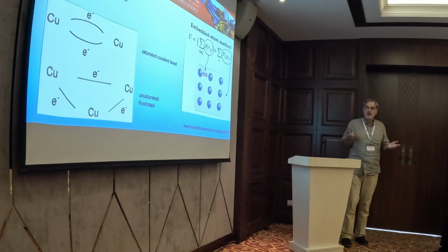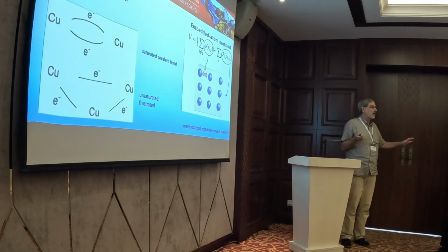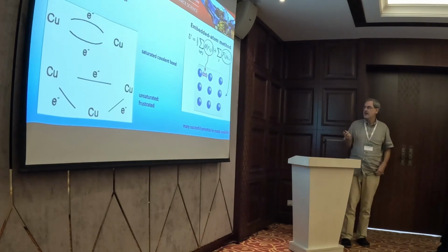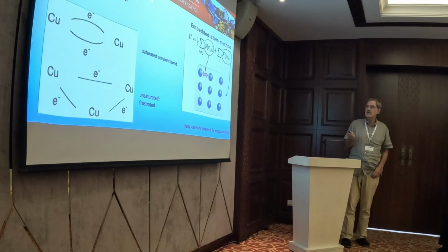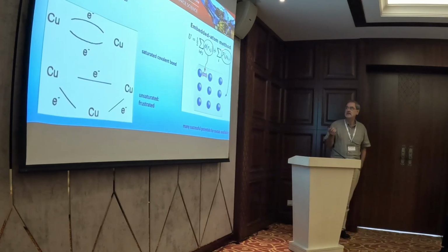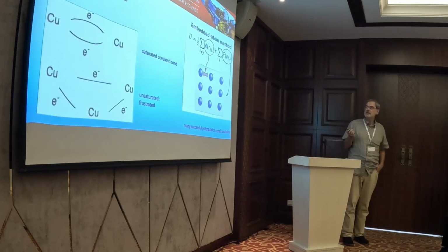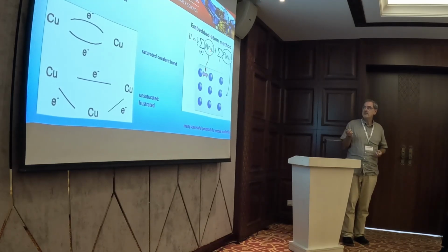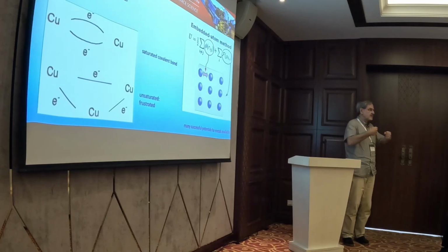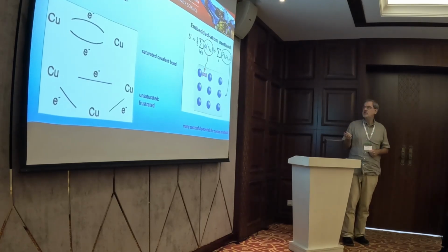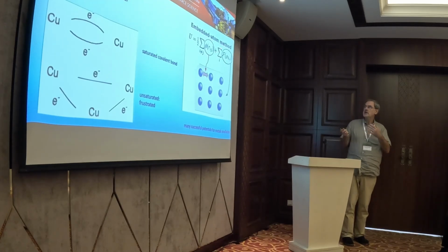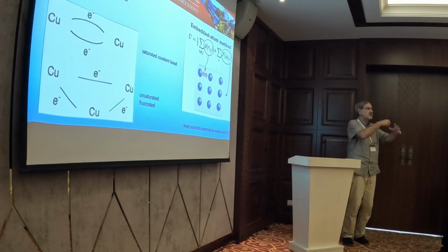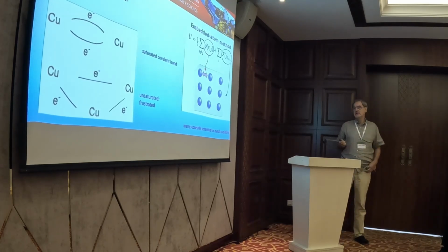And this means, since now 40 years, we know how to do this. We know how to describe metals, metallic bonds, and also other bonds. And this is done with the concept of many-body forces. The famous example is the embedded atom scheme, which is used for metals. So for the potential energy of the entire system, you have pair forces, which basically describe the repulsion of atoms when they come too close. But you also have a many-body term which describes the interaction of each atom with the electron gas which is around in the metal.